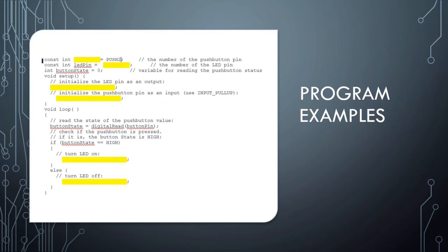So in this first line here, we are going to declare or give our push button a name. This is where we're assigning our variable names. And so here I've used push2. Remember, we used push2. That is correlated to pin 1.3. Our pin, I believe it's 14 if you have the EX microcontroller model. So we can use any of those if you didn't want to put push2 there, but you need to identify it with a label.